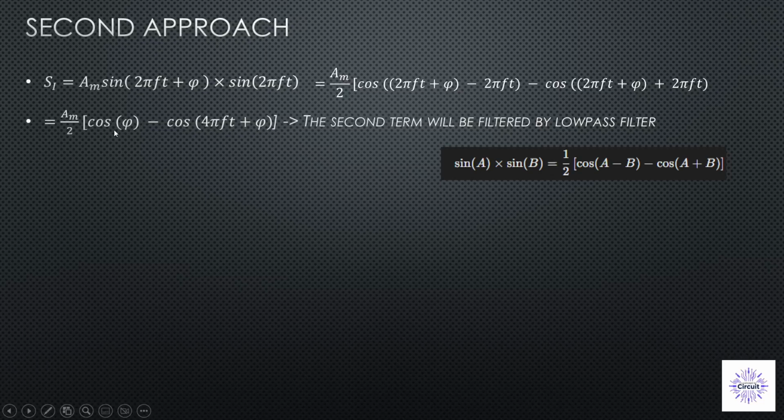Now we have an interesting situation, because we have a DC signal, meaning that it's a constant, it's not changing over time, added to a time varying signal that changes over time, right? With frequency equal to twice our signal frequency. This is actually 2 pi 2 ft, right?